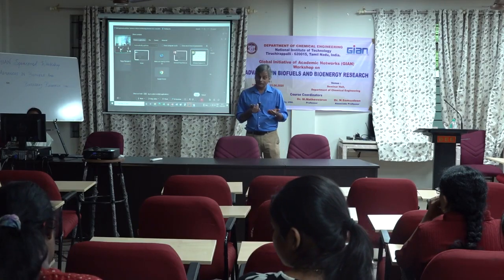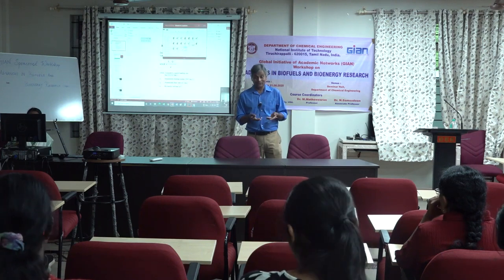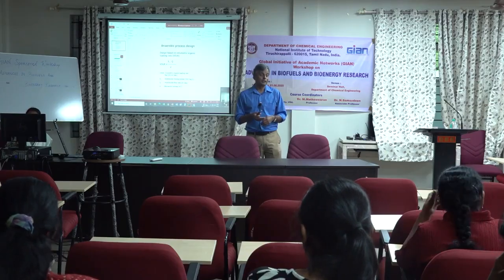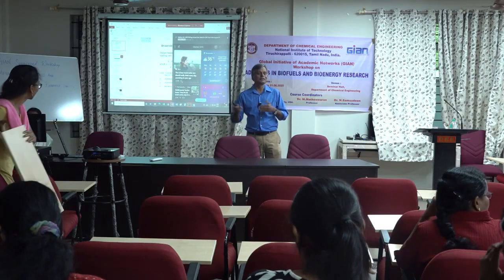So in order to know this, you need to do analysis. You need to know what is in your waste. You do COD analysis, and you need solid analysis if you do solid loading rate. You cannot just figure it out. You need to know those parameters. If you know the parameters, you can calculate it. Okay?